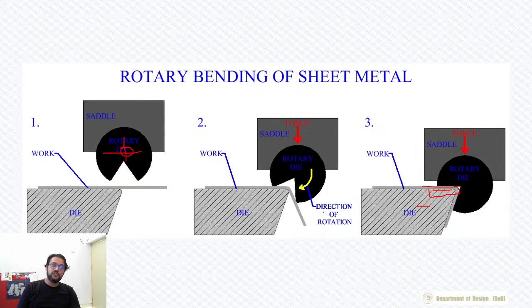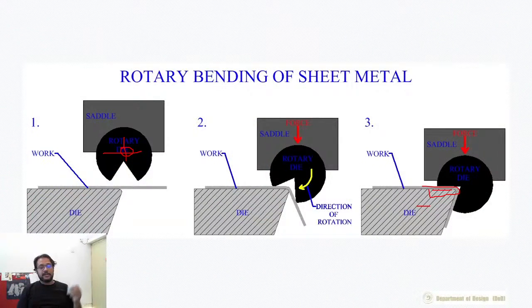One of the things that you should know about metal bending is this, right? So you have this, you bent it, and when I remove the force, what happens is that, let me go to full view. So what happens is that it, did you see, it comes back. So I held it between this piece, I wiped it, and it's supposed to retain this kind of shape. No, it doesn't, it will come back a little bit, and this is called the spring back of the sheet metal, and it is one of the key things to consider when you are bending.